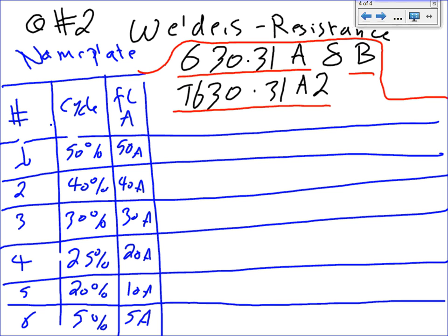Okay, let's start with the first one. The first one, guys, is 50 times the multiplier based on the cycle, which is 0.71. Yep, 0.71. And I'm going to do this in a different color, based on the largest. Is 50 the largest amp welder in the system? Yes. Then if you look at B, it tells you this has to be multiplied by 100%. So this is where the 1 comes from, in green. Mr. Rebel, you're going to ask me where this green 1 came from. This is from B, where it tells you the largest welder, leave it alone, multiplied by 100%. Piece of cake.